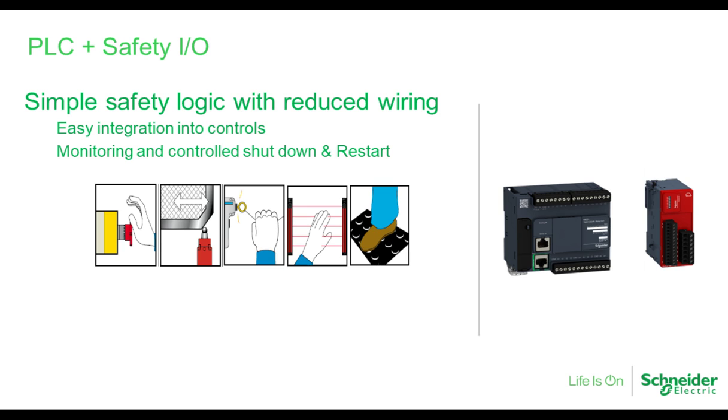There's also a lot of products out there where you have a regular PLC, I'm going to call it, and you can add safety logic to it. Sometimes it's as simple as what I show here, which is basically a relay. And the advantage here is that you have the ability to see the status of that safety controller or the safety relay without needing additional wiring to your PLC. But there are other products.